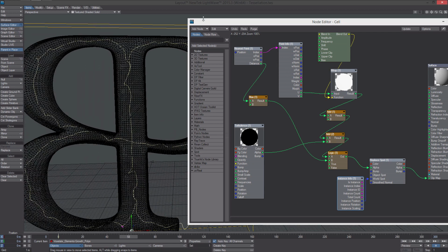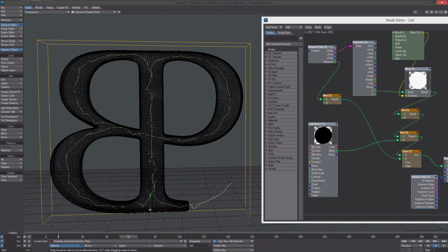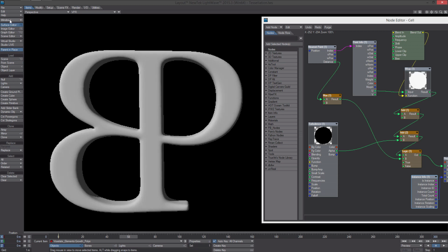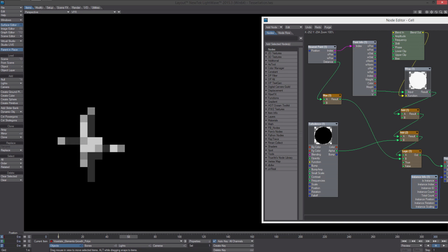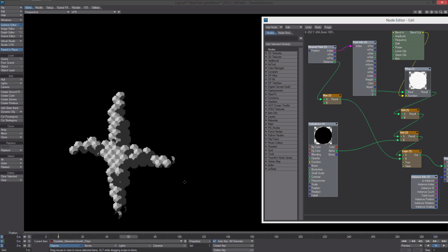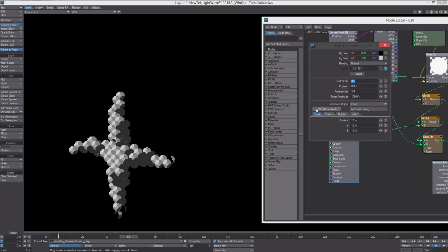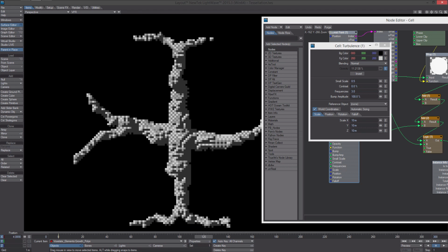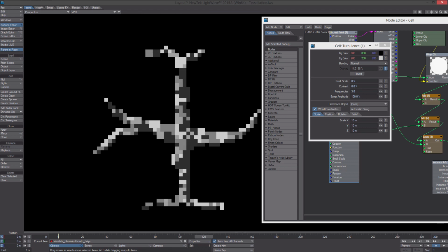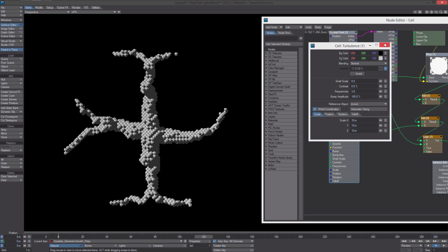And you'll be able to see now that we got to turn our B off for now. So you can see now it's only going to show the instances where that. Now keep in mind, this can also be done with procedural textures. It doesn't have to be the texture we made. Now I'm putting that texture on world coordinates. That's important, because if it's not, it won't work properly. You got to make sure that that turbulence texture that we created is in world coordinates. And now it'll work exactly as it's supposed to.